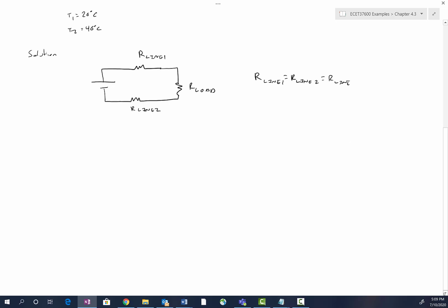Remember, we don't do that in three-phase because the currents flow in balance in three-phase. They cancel out in the neutral, so you don't include the effects of the return current in three-phase. But in single-phase systems, you have to. You get that additional voltage drop across the conductor that connects back to the load because there is current flow through it. It's not true in three-phase. So if you notice, we didn't do this in three-phase systems. That's why. We assume balanced operation.